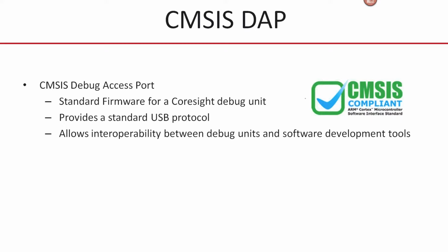So again, we've seen that many very low cost evaluation boards also feature a debugger. So these are CMSIS-DAP. There are also other similar systems like ST-Link, and I think Segger also provide a similar system. So now the actual cost of getting a basic debug connection is very low.